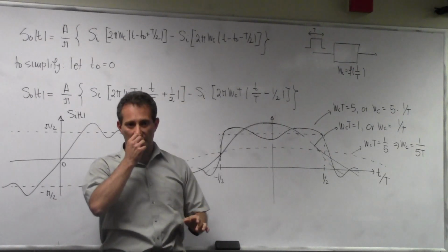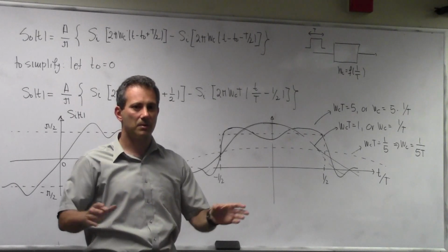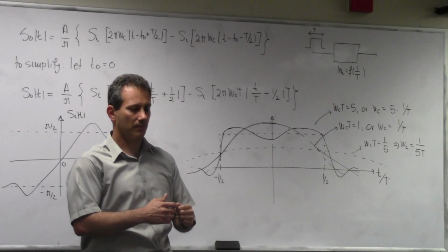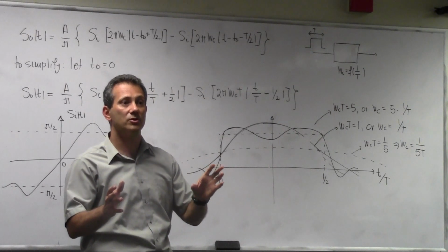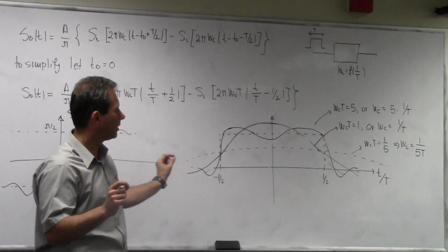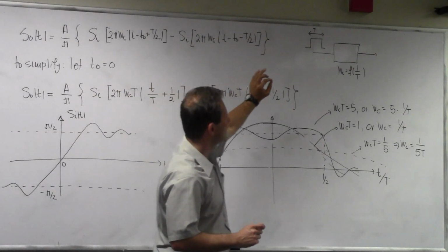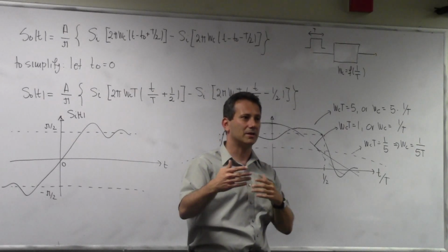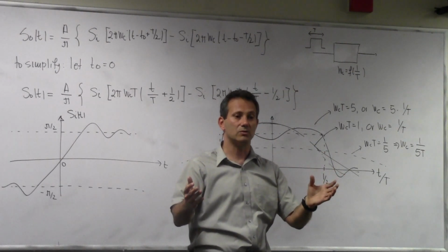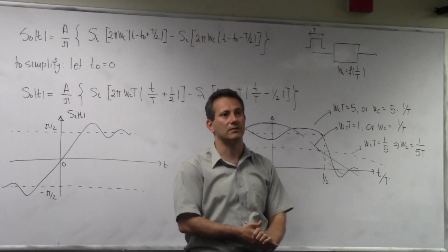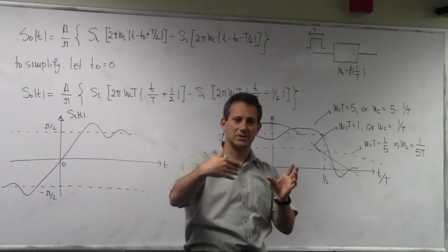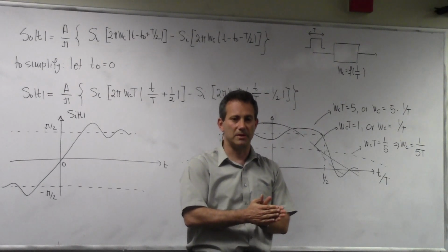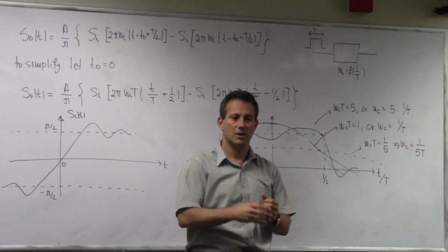And to do that, we approach this in two steps. In the first step, we have to understand what the spectrum of a digitally modulated signal looks like. So far, if you follow what I did here, I looked at a single pulse. For a single pulse, I know how to do the Fourier transform. But when there are many, many pulses coming one after the other, I end up with a digitally modulated signal for which I need to derive what the footprint of that signal looks like in the frequency domain. Because it's not only a single pulse, it's many pulses coming one after the other, modulated with the bit sequence that I'm using to modulate this pulse stream. So that's our first step.